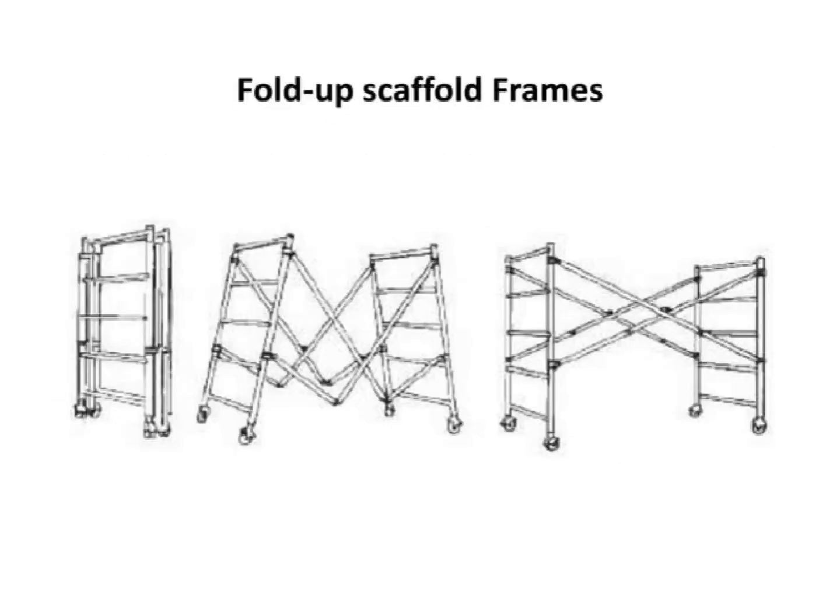Scaffold frames that fold up are a common feature of worksites where working at height is necessary. It is important to inspect these frames for visible damage and wear before and after use. If any damage or wear is noticed, the frame must not be used. Additionally, users should always adhere to the manufacturer's instructions when using these frames, in order to minimize any potential hazards to both workers and those in the vicinity.